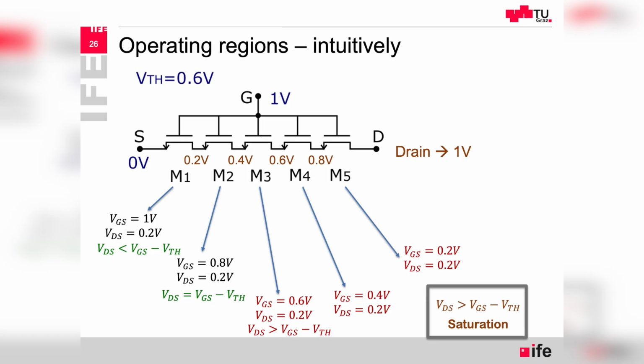And now when we analyze what happens at each little transistor, let's make an assumption, a very simplified view. We can say, what if we have the drain voltage equally distributed along the channel, so we have 0.0 volts, then 0.2, 0.4, 0.6, 0.8 at each source of these little transistors. Then the drain to source voltage in that case, if we simplify like that, would be 0.2 volts.